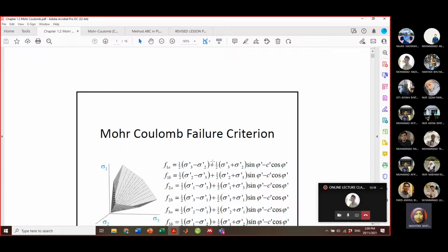As I said, some of the material will behave differently according to the type itself. But the part is you have to be familiar with the material parameters, and how it behaves when it is subjected to loading, whether in undrained or drained conditions. Either you are using the correct effective strength parameters or total stress parameters. So these are the things that you have to check before assigning in the numerical software.